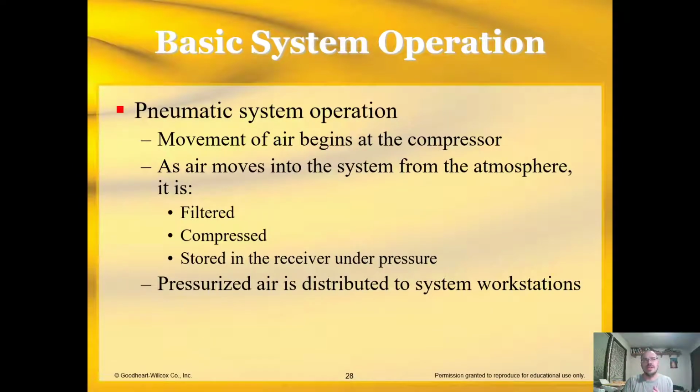Pneumatics, this is different. In pneumatics, movement of the air begins at the compressor. The compressor draws air in from the atmosphere, right? As air moves into the system from the atmosphere, it is filtered, compressed, and stored in the receiver under pressure. The receiver is those big tanks you see. We'll talk a little bit more about the reasoning for having those, but that's where all your energy is stored.